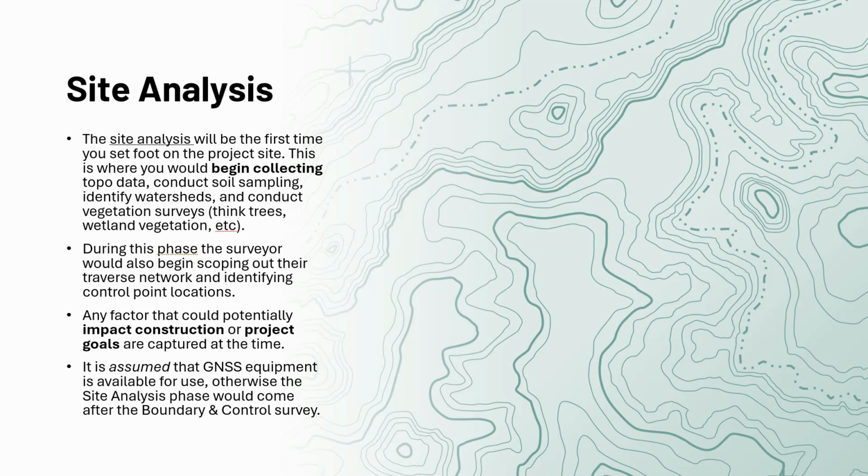Is this a construction project? Do I need to set up certain monumentation to leave back to continue to reference? If you're doing a wetland study, if that's the overarching project here, you're going to have to establish control that's going to survive that environment and last long term. Where's going to be the best point to establish that? Really, that vertical control is most likely what you're going to be looking at that point. And you, the surveyor, start thinking about all that when you see the site in person during your site analysis.